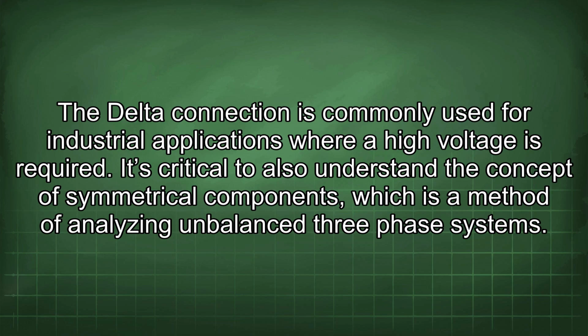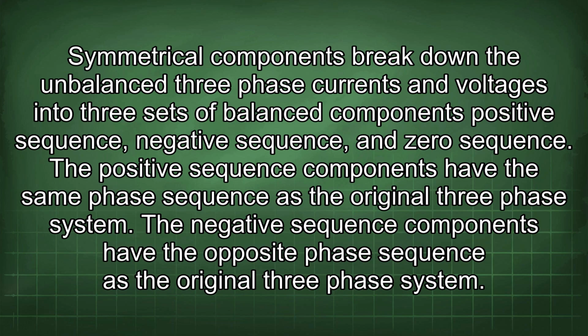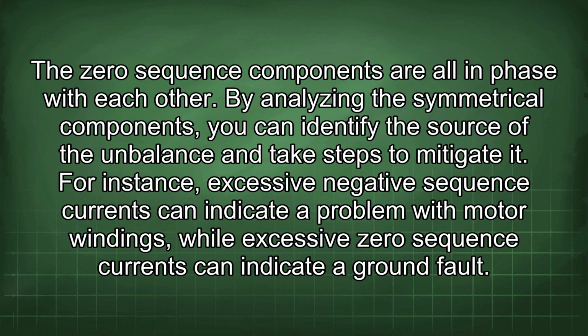It's critical to also understand the concept of symmetrical components, which is a method of analyzing unbalanced three-phase systems. Symmetrical components break down the unbalanced three-phase currents and voltages into three sets of balanced components: positive sequence, negative sequence, and zero sequence. The positive sequence components have the same phase sequence as the original three-phase system. The negative sequence components have the opposite phase sequence as the original three-phase system. The zero sequence components are all in phase with each other.